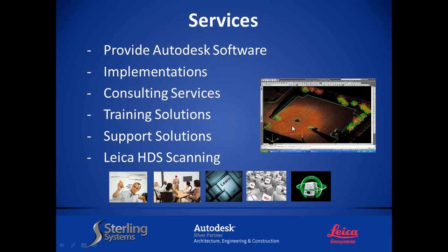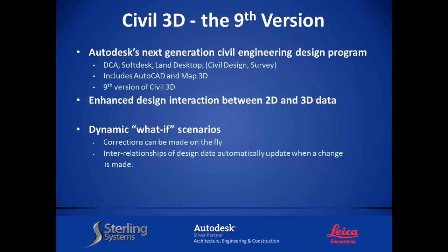As you can see there, there's a picture of a parking lot. The scanner was actually set right here in the center of the parking lot. Anything you could see, it brought into the screen in Civil 3D, and then I actually created a topo with that data. So I have a field book that was brought in and processed on top of that point cloud. And the best part is I can see, as a surveyor, if I missed any of the parking lines, the trees, utilities, everything. It's like I'm at the field to help verify that.